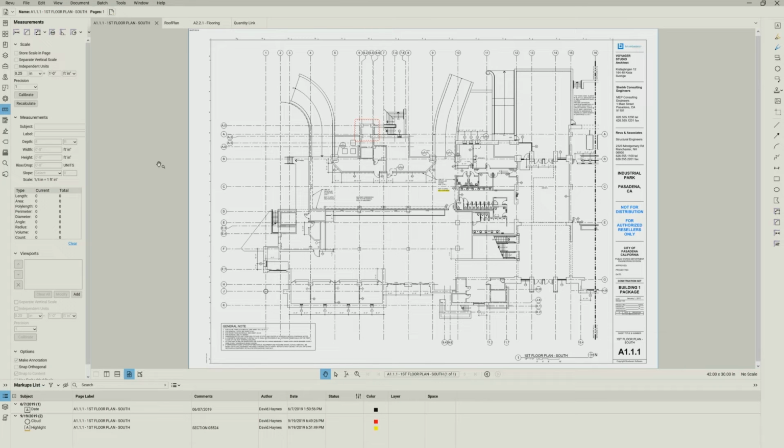And that's really for vector-based drawings, meaning ones that have been created by vector-based. If you've gotten a PDF that's maybe been created by a very cheap PDF creator, you may not be able to snap to the content. Then I'll show you another way we're going to want to do. All right, the next thing is we're going to calibrate this to get a scale. Also with vector-based, calibrate will work very well, but you can also use typed in for not vector-based.